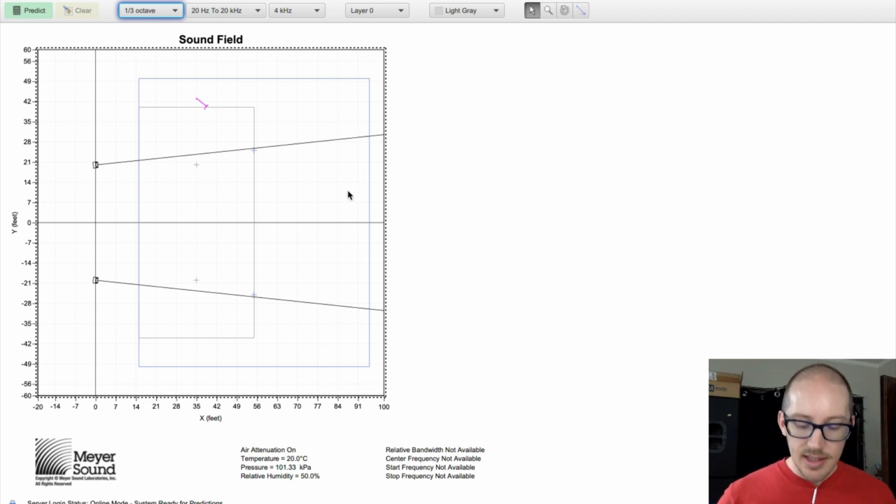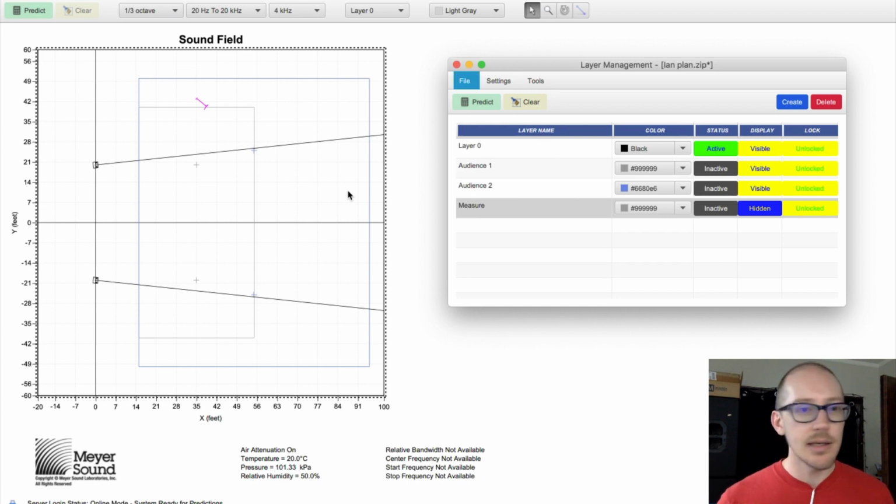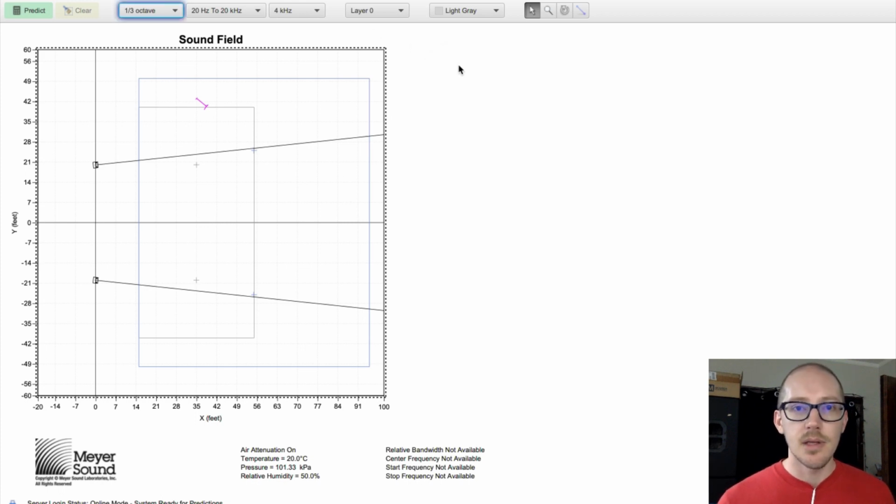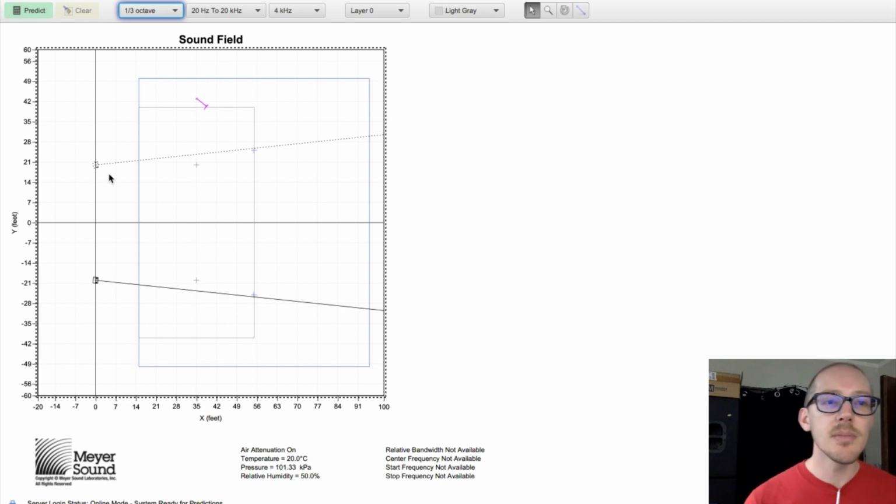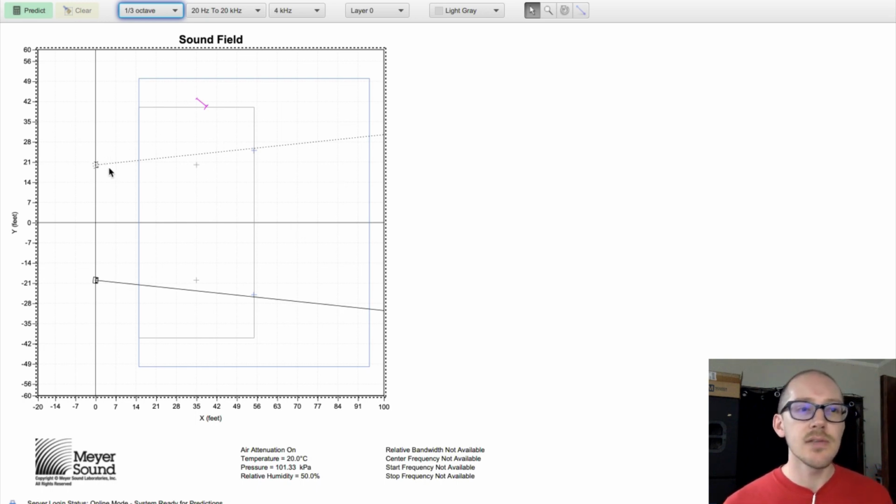Okay, so I think that's all I wanted to say about the aim. You asked about the placement. We talked about placing near the center of the coverage area. You wanted to know about the aim, and you were thinking aim inwards, but because each of these speakers is kind of assigned to one half of the room, I would actually focus more on aiming them through the center of their coverage areas, where I drew these pluses.